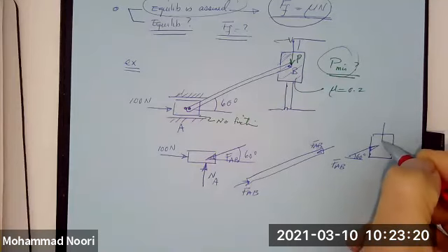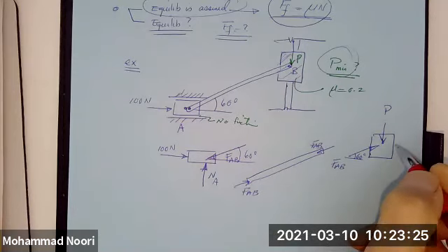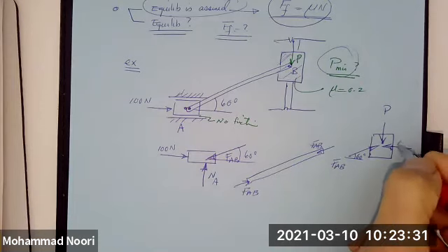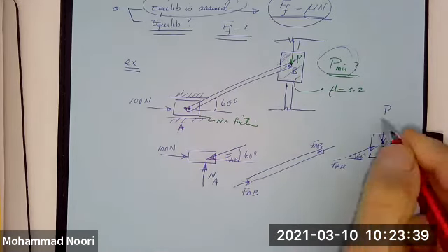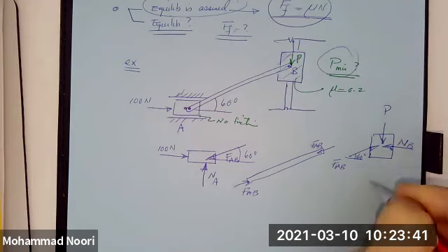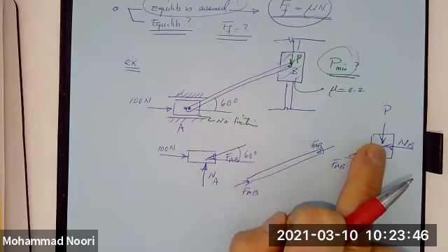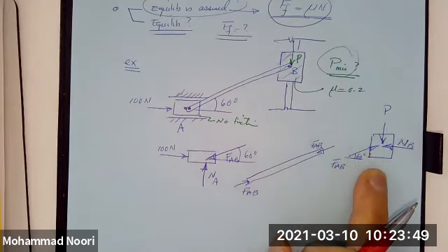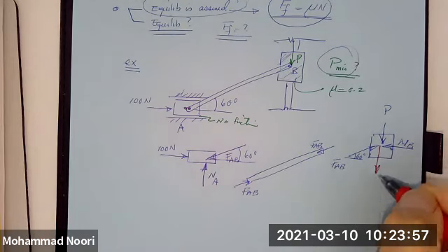You have an applied load P here, and a friction, and obviously this goes up and down against this rod, so you do have a vertical reaction force perpendicular to this direction of motion. And then there's a friction force that is going to basically resist the motion. But since this piston, due to the action of this force, would potentially cause a motion upward, therefore the force of friction that would develop here would be downward.